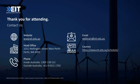And lucky last question for the webinar. Zibs, IP rating depends where it goes. Externally, I'd suggest 56 or higher. Internally, we typically use 42, but it's up to you and what your application is.